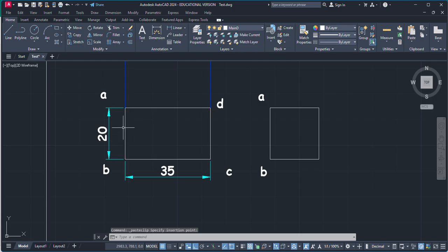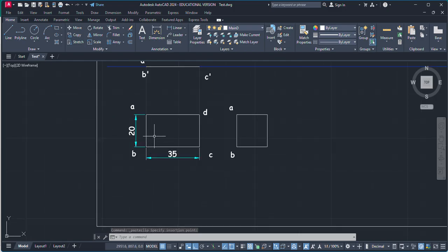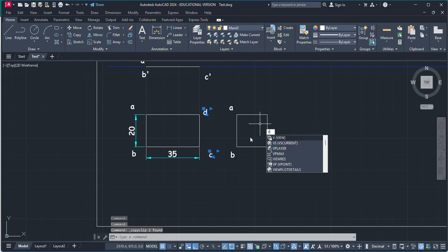This is the resting edge, and while resting on this, if we rotate this thing with the HP, this length is going to compress. So we can assume, because it is given in the example, in the top view you will have a square, so this length is going to be reduced by 15, final length will be 20. So we have created this square. This one is 3.